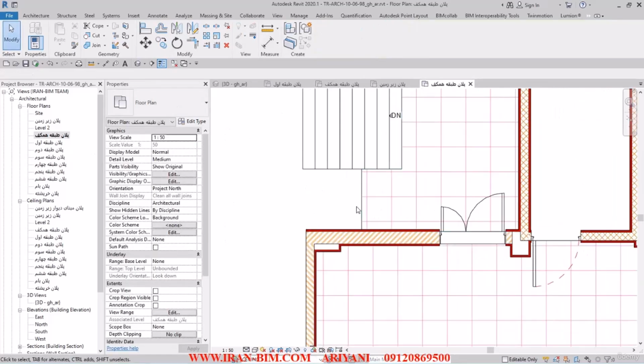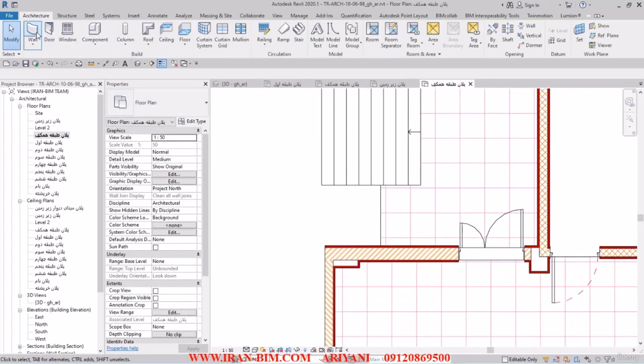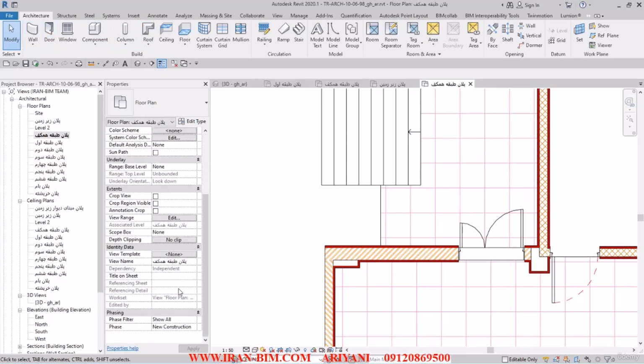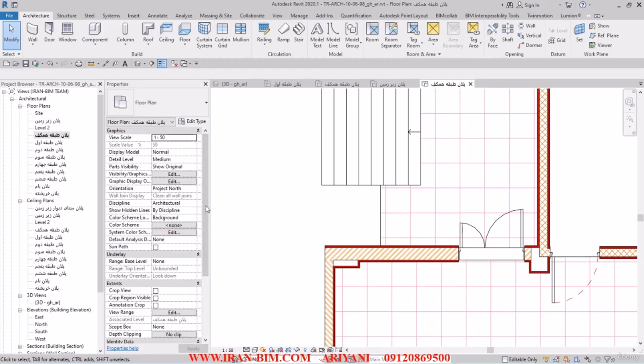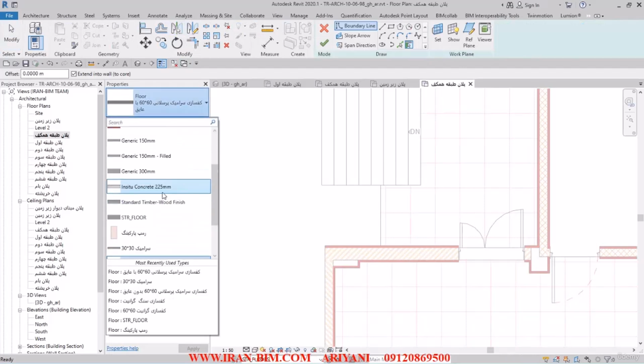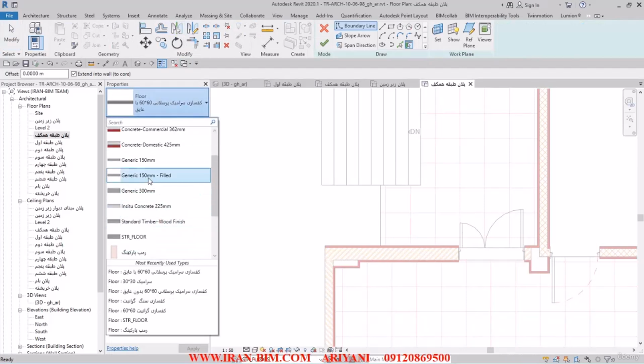Here I'll choose the floor tool. And after that, we need to put the work set on the floor. Let me see where it is. Just cancel this. So here from this menu here, we'll find the floor. Here we'll select stair floor. There it is. And after we've done that, we'll just select the floor tool using some 150 millimeter tile.